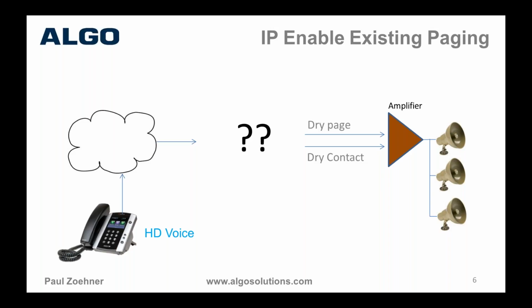So what we see often done is an ATA is provided that will then interface to the amplifier. But in this case, that amplifier won't play nice with an ATA because it doesn't have the ability to answer ring. So it does not accept an ATA, an FXS port, or a station port, as we would call it. You could install there an ATA and a telephone answering module, but that's a fair amount of equipment, and as you'll see in a few slides from now, you also lose some audio quality and have some other issues.